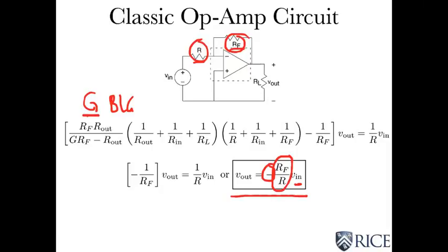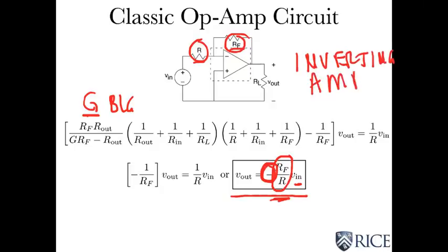They don't matter as long as we have a big input and big gain. This result applies. So we control the gain. Do note that it inverts. Remember, a negative sign corresponds to inversion in electrical engineering. So this is an inverting amplifier. That's the name for it.